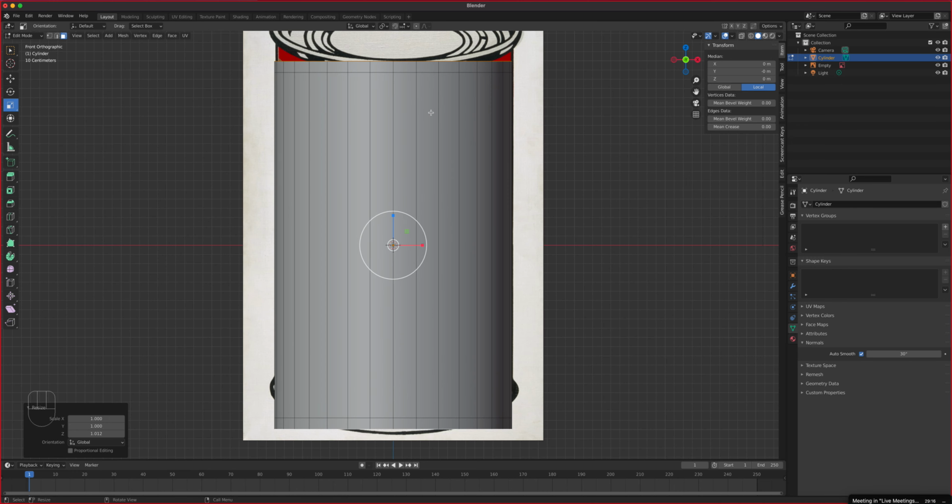All right, so here what we'll do is I'm going to do a loop cut for the top and the bottom. You can use the loop cut tool right here. When you click that, you can position on a horizontal line, then you get a vertical cut, and vice versa. If you position your cursor on a horizontal cut, you get a vertical cut. Vertical line, you get a horizontal cut.